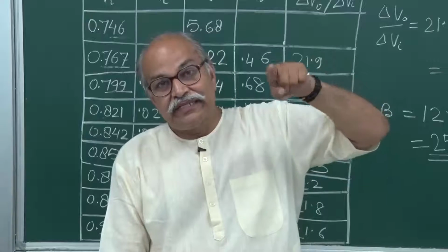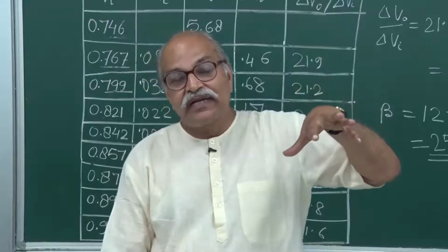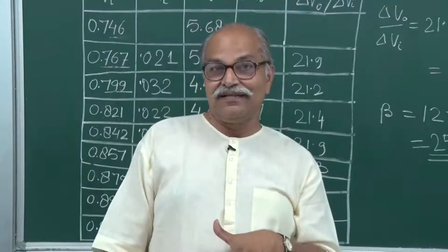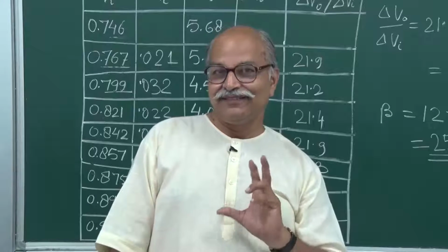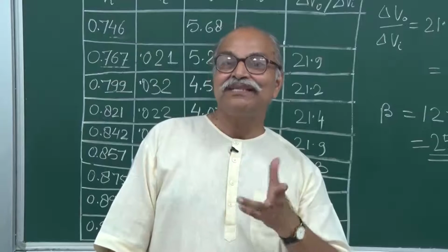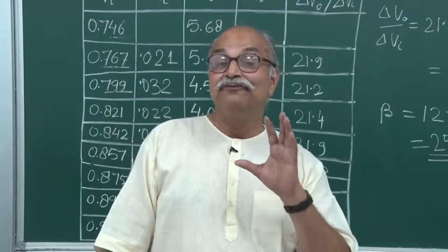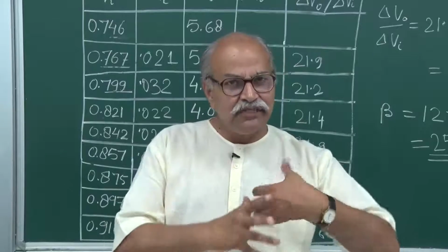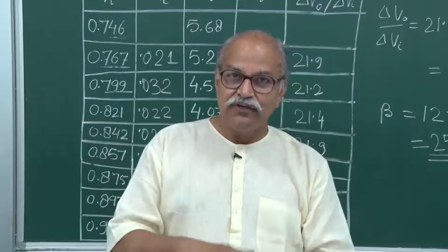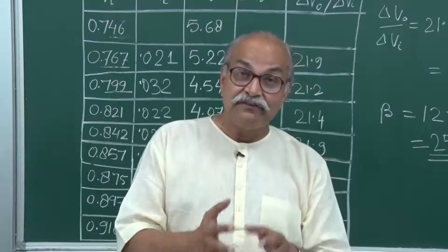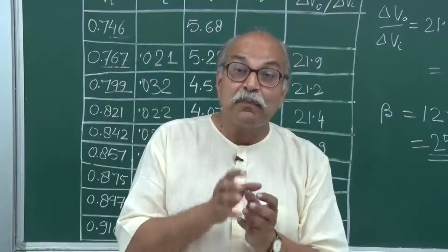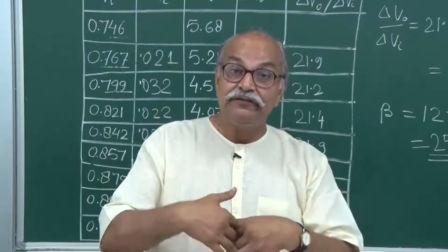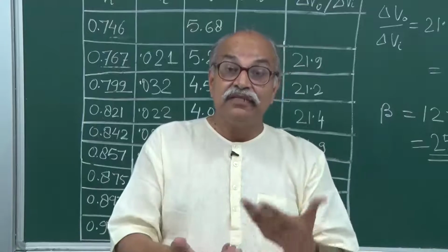So what you are doing is you are controlling a large current circuit through a small current circuit. You are actually doing switching. You are doing switching in that base circuit, that VBB, that forward bias of the base emitter junction. You are somehow changing that voltage from a low value to a high value. The voltage that you apply to that base circuit, you change it from a high value to a low value, from a low value to a high value. That is the switching.